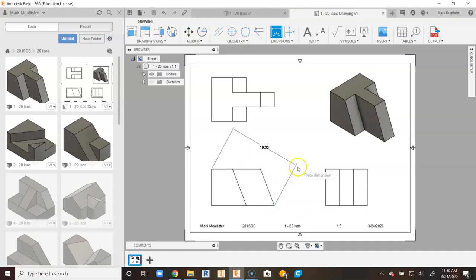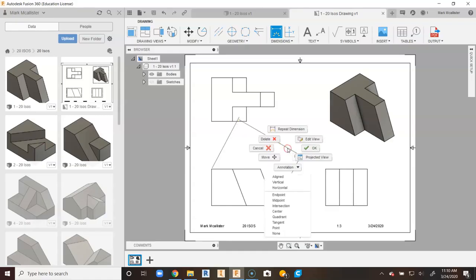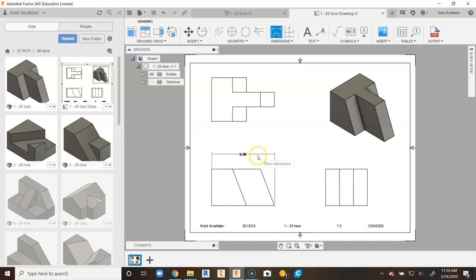And you're going to notice at first, you're like, I don't like the fact that it's giving me this diagonal line. While you're dragging out, you can just right click and go down to horizontal and drag up. And notice you're going to get these nice convenient snaps when you do that. Now, I know that within this object, I have 3 distances that I'm going to place from baseline to here and from baseline to here.